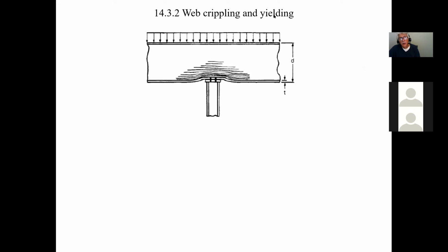This is what you have. Can everybody see what's happening? Okay. Because the forces are going down here, this is similar to the bearing resistance for the wood. We want to make sure that BR is good enough. Well, here, you want to make sure that the web that you have for your beam, when the load goes through this, doesn't start crushing, okay?